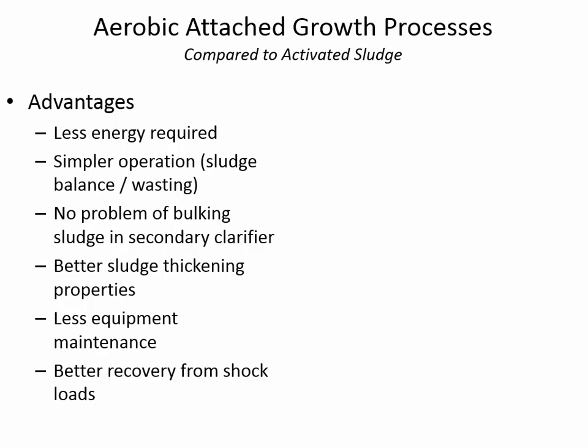And we've talked about where is the majority of the expenses in wastewater treatment. Probably at the top of the list is electricity, moving water from place to place, aerating the secondary treatment. Another one of the big expenses is dewatering sludge. And here in Huntington, when he was saying that on average, I think he was saying that they have 4 truckloads of sludge going to the landfill each day. So if you were able to concentrate a sludge from 1% solids to 2% solids, that would cut the volume of sludge in half that has to be disposed of.